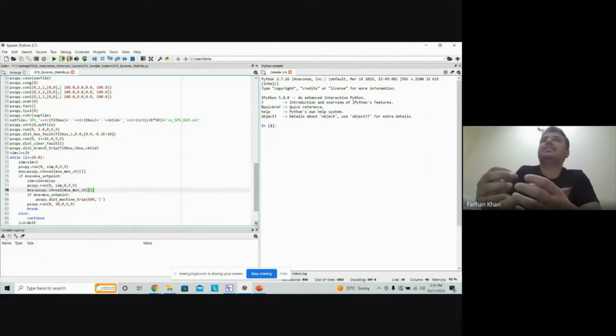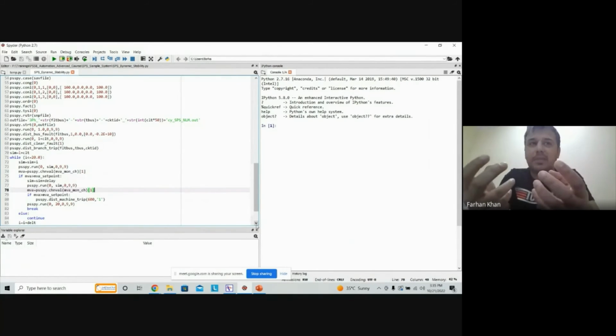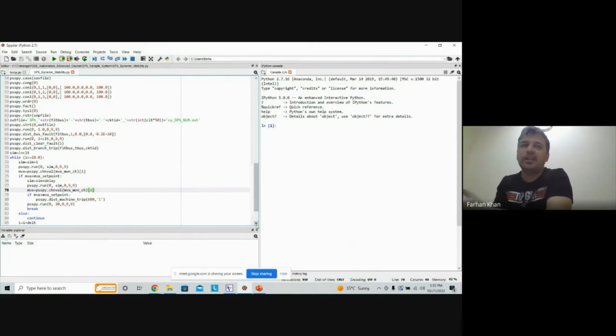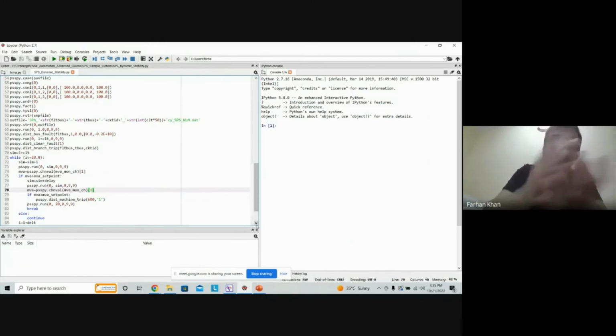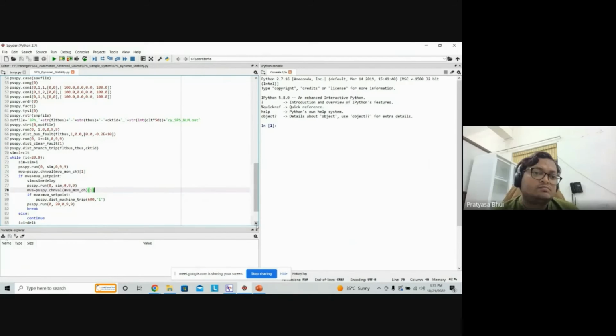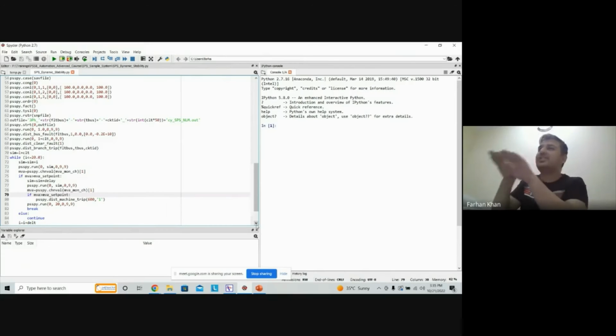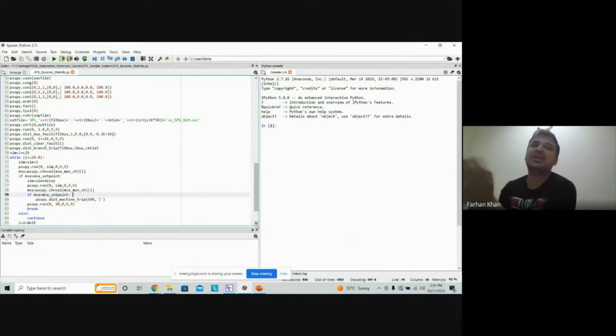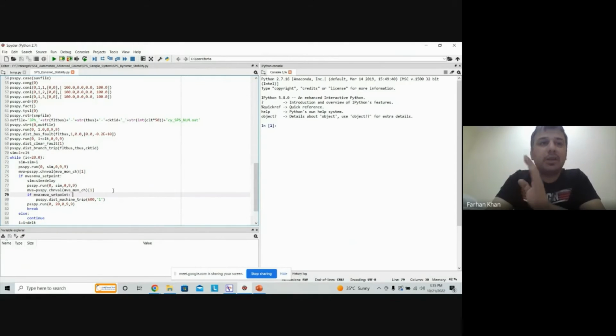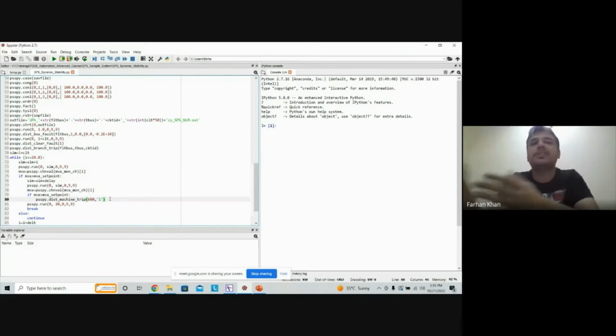whether I'm still getting some kind of overload or not. It's again just kind of playing with these things. This is a theoretical thing, but what you are trying to do will be something practical, so you have to adjust it according to your own need. Once again, I'm making sure whether still after this peak of 1 second my line is overloaded or not. If after 1 second my line is still overloaded, just trip one generator. The generator which is available at bus number 600 and its ID is 1, just trip this generator.